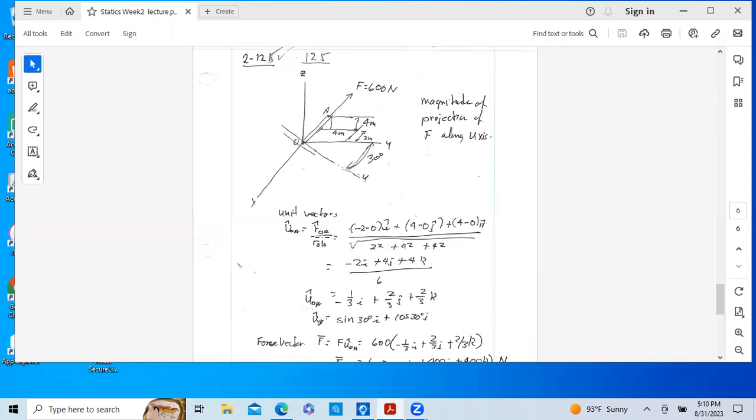And so the unit vector O to A is the ijk dimensions divided by the magnitude, again, a square root of the sum of the squares of the components. And so the unit vector O to A is 1/3 i plus 2/3 j plus 2/3 k.